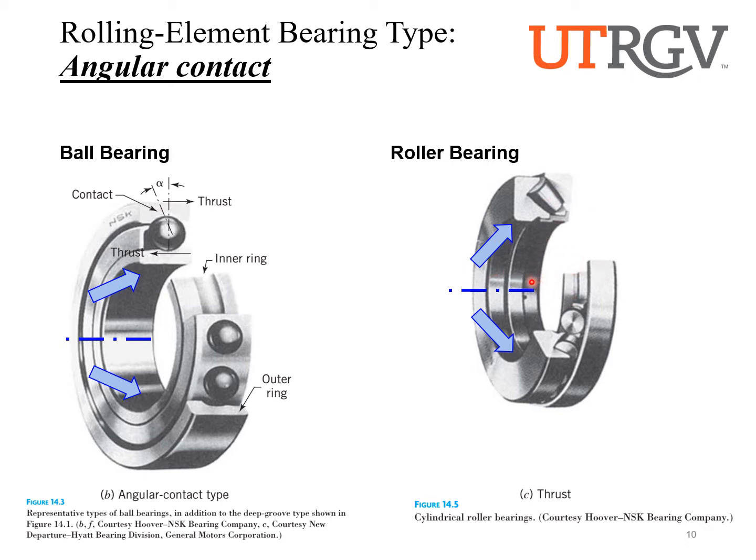So I guess to be more technically correct, if we go back to your statics problems, there are the journal bearings and the thrust bearings. Whenever the term thrust bearing came about, usually in application, the bearings that we're using are the angular ones, because again, they're going to take radial and thrust load at the same time. If we remember the picture of the thrust bearing in the previous slides, those bearings cannot take, or they can take very little, radial load.